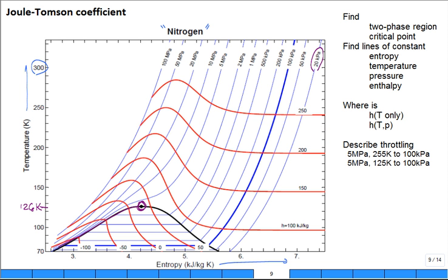They have a line of constant pressure. See that? 20 kilopascal, 100 kilopascal, 1 megapascal, all the way up. So these blue lines swooping down are lines of constant pressure. Why is the 100 kilopascal thicker? Because it's atmospheric pressure. And 20 kilopascal, we'd say it's a vacuum. What other lines of constant H? Look at here, the red lines. They're constant enthalpy, aren't they?